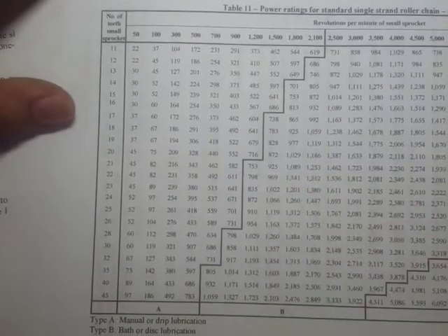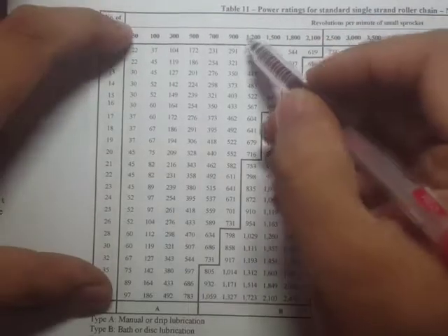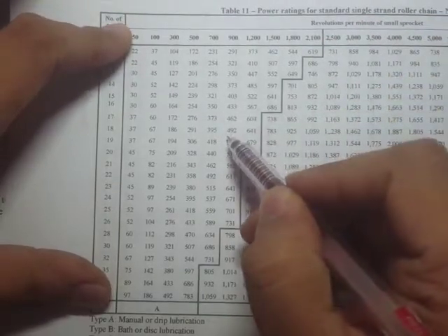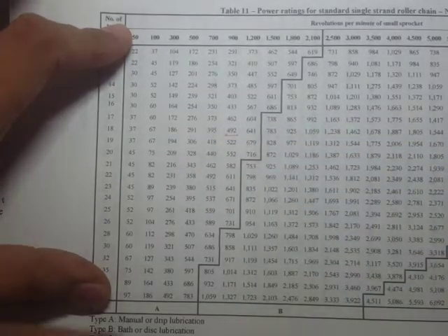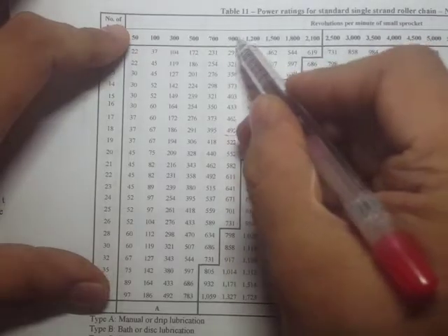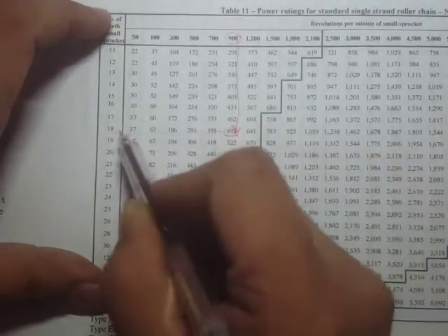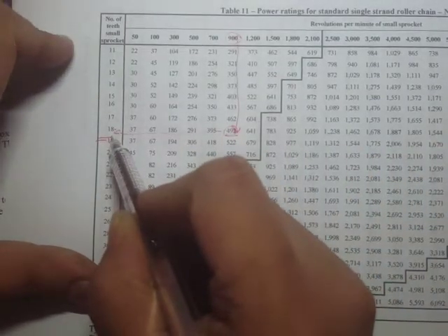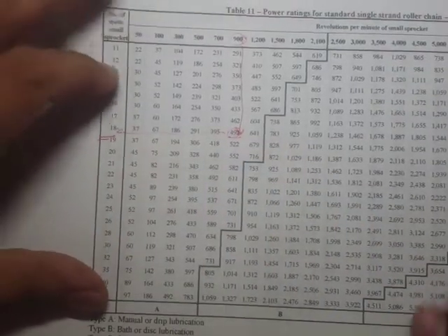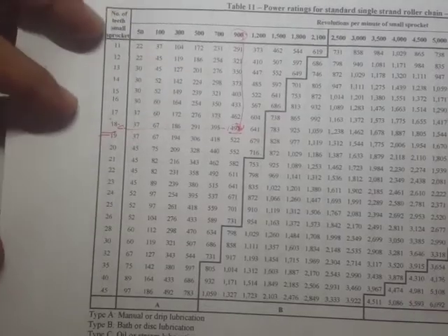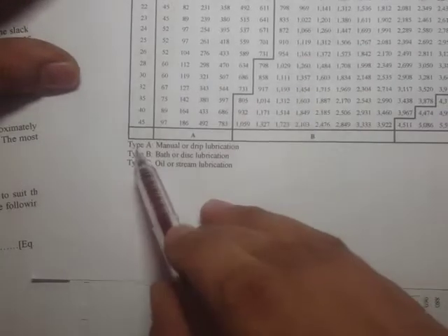So our selection would be, how do we know the number of teeth? We can compute the required power through the design power equation. If you have this 900, you know this is speed, and you go down here so you can get the number of teeth of that small sprocket. Once you have that, you just apply the speed-teeth relations to obtain the other sprocket.